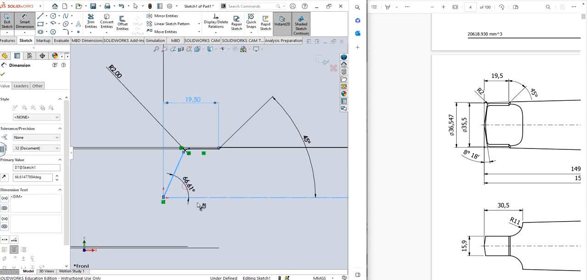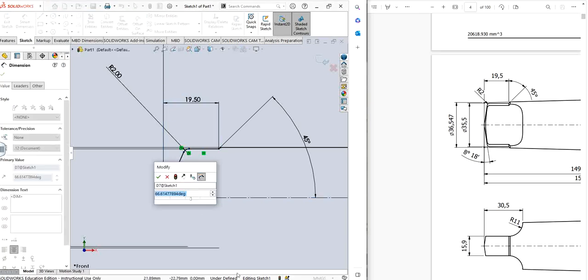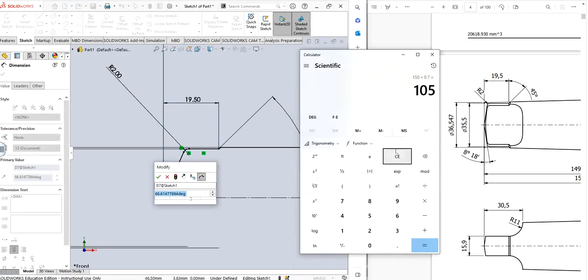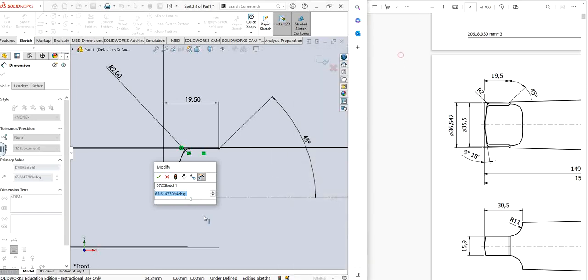So I need to do some maths here before I do that. So it says 8 degree and 18 minutes. 18 minutes divided by 60 will get degrees, so 0.3 degrees, so 8.3 degree. Alright, 8.3 degree minus 90 is going to be 81.7 degree angle. 81.7 degree divided by 2 is going to be half of it.